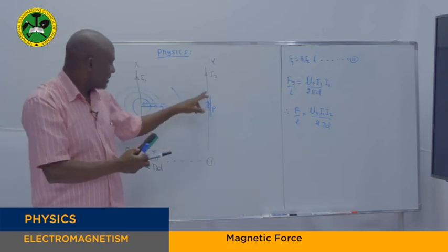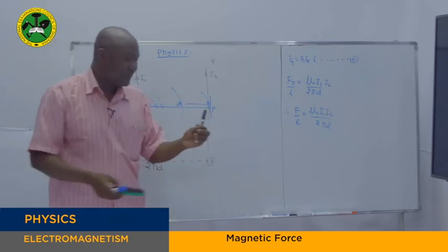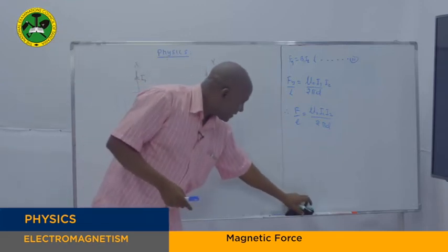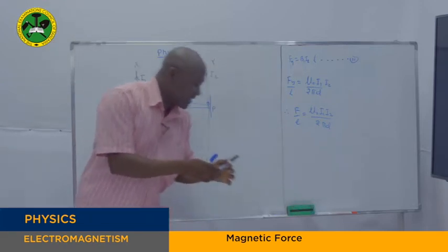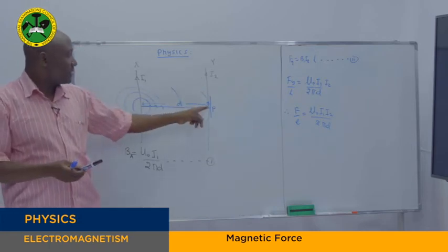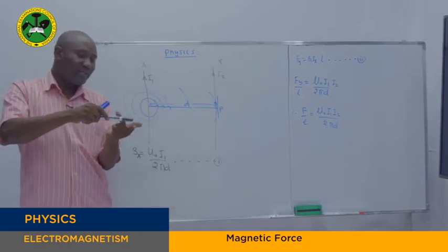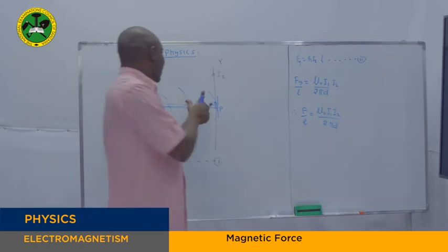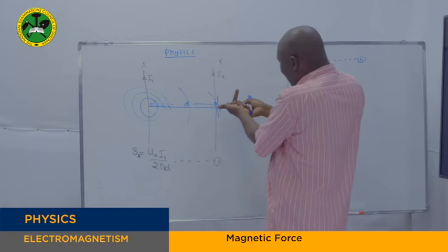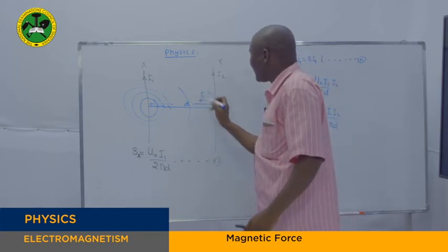And you know the magnetic field, the magnetic flux density, is acting into the plane. So here, into the plane. Our second finger, which talks about the current, will be pointing upward here, while the magnetic field is in. Can you see here? Current is up, magnetic field is into the plane, so the force created here will be pointing like that.